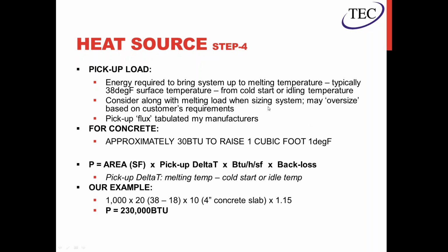You definitely want to consider the pickup load when you're tabulating the melting load, and depending on the system, the amount of pickup that you want to allow, I should say, will be variable on the type of system, because it is going to oversize your heat source to some degree.